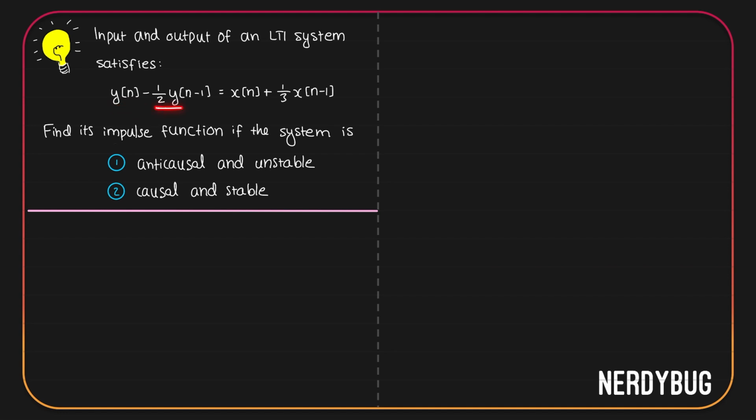y of n minus half y of n minus 1 is equal to x of n plus 1 by 3 x of n minus 1. We have to find the impulse response if the system is anti-causal and unstable, and when it is causal and stable. We have the difference equation here.